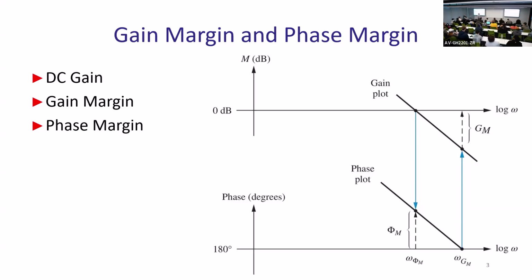And this is that point. So you have phase margin, which is above the 180, negative 180, depending on where you are at that point. If you want real phase margin, when you have multiple crossing points of gain, and gain will go up and down, again, you are picking the worst case, where the phase margin is the minimal. This is the overall phase margin of the system.